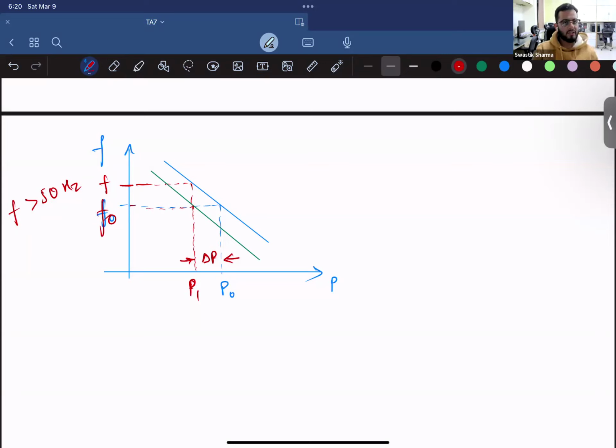So what this droop control does is shift this curve up or down based on whether your frequency has decreased or increased, and then it matches your P1, which is your new equilibrium point, to maintain the frequency that was there originally, which is your normal operation. With droop control, you shift your curve in a way to match your normal operating frequency at all times. So that is how your droop control works. It produces a change in your coefficient. Is this dependent on frequency?